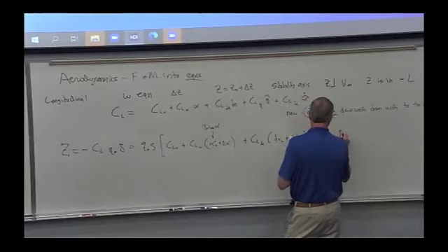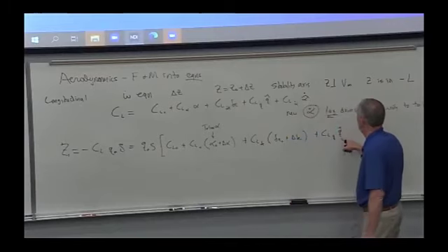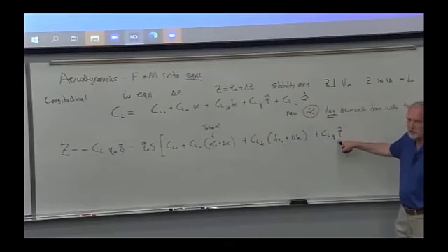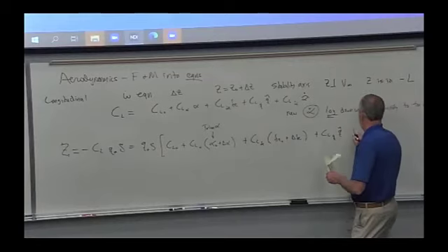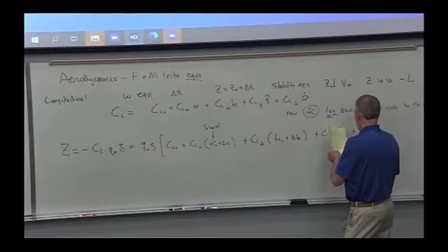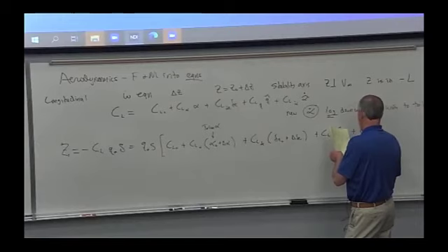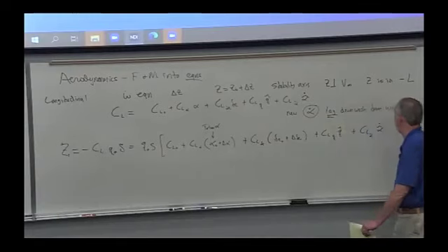And we don't have to differentiate that with the Q term because remember, with the trim condition, there is no Q. So this is just the perturbation. And the same thing with the alpha dot term. There is no change in the angle of attack in the trim condition, so there is no alpha dot 0.